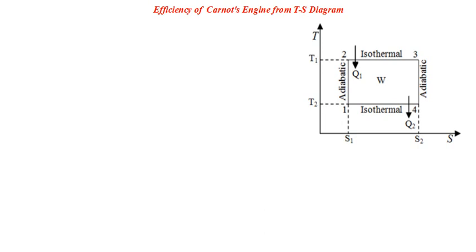Now during this heat transfer, since heat is entering the working substance, what should happen to the entropy? You can understand what should happen to the entropy. The entropy should be increased, because that is our idea. Due to the heat entering a system, the entropy of the system should be getting increased, and when the heat leaves the system, the entropy of the system will be getting what? Reduced.